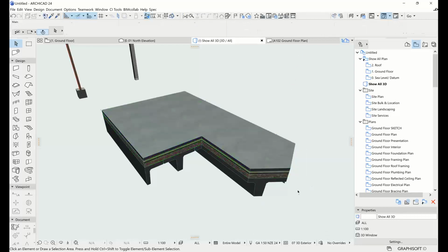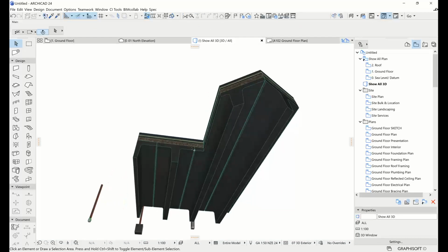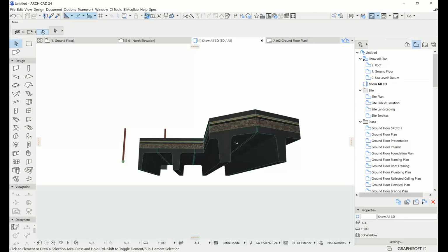Update the precast covering to trace that shape as well. You can see that we've got lines separating each individual piece, which is what you were seeing in the floor plan view here, and the hidden detail line is showing the shape of that T there.